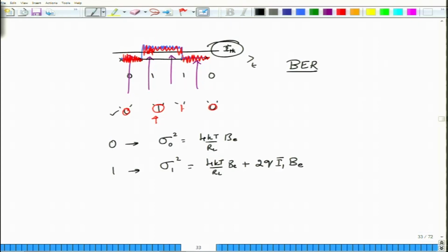Now, we have written down the variances sigma 0 and sigma 1, and we have said that these are the variances of the noise sources, but we have not fully characterized what kind of distribution this noise possesses. We will assume that these are Gaussian processes, which means that the random variables that you obtain after sampling the photocurrent will be corrupted by noise, which is itself a random variable, and that random variable is Gaussian distributed.